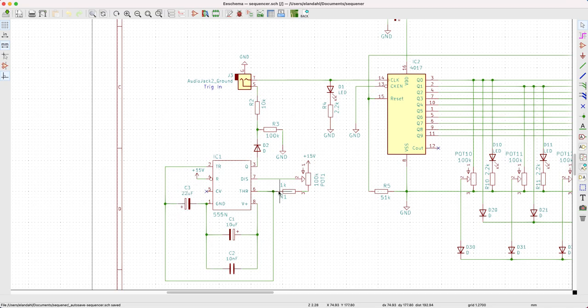it's when it passes the threshold value that will cause the output, which is here labeled Q in this place. This is the output of the timer to switch. A diode prevents currents from running back in, perhaps from the external source. And there's a 10K resistor in series to make sure that when a plug is put in, that when the site is grounded, the timer continues to run just fine. So those are the main features.